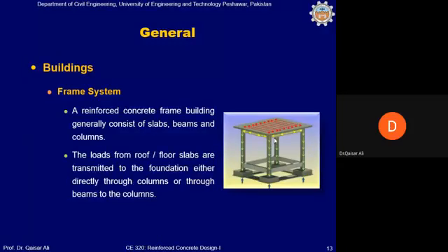Okay, so the foundation, particularly in this case as shown in this slide, is like an isolated footing, and the foundation will be bent at the edges, and the bending moment will be such that tensile stress will be produced in the lower part of the foundation pad, and compression stress will be produced in the upper part of the pad. And it is possible to design structures without beams, where the slab will be directly resting on columns. It is possible.